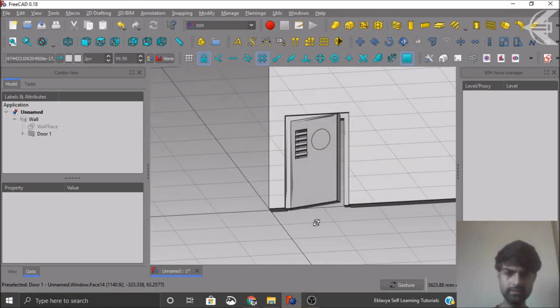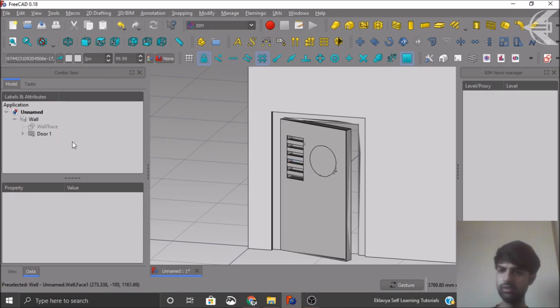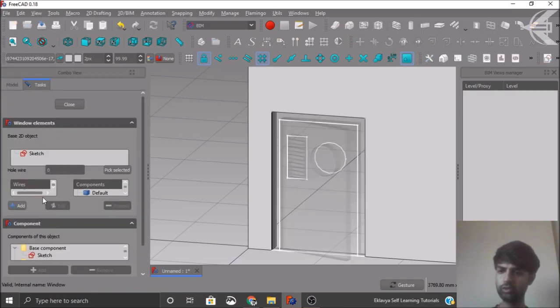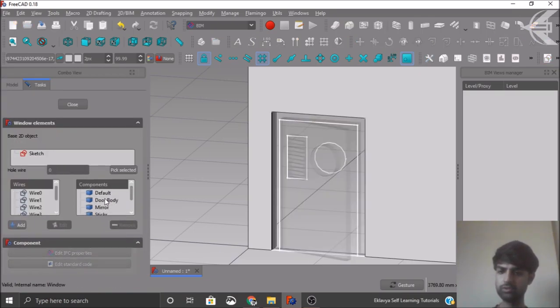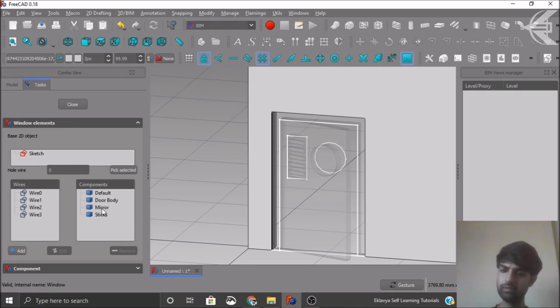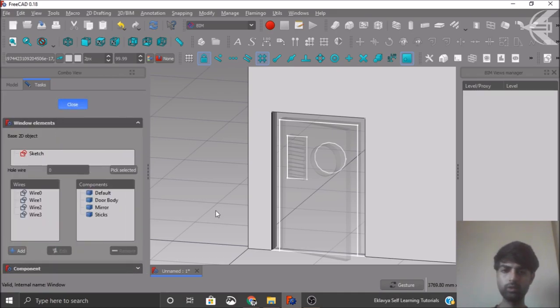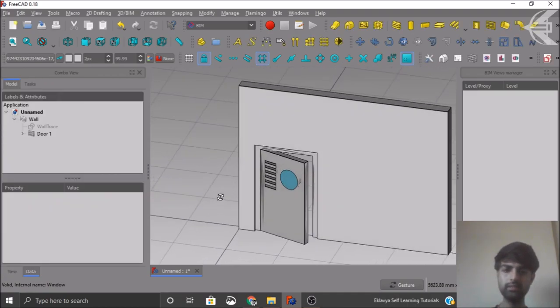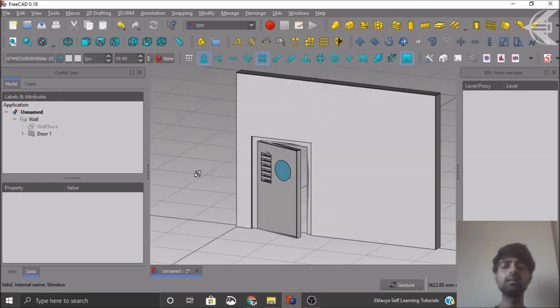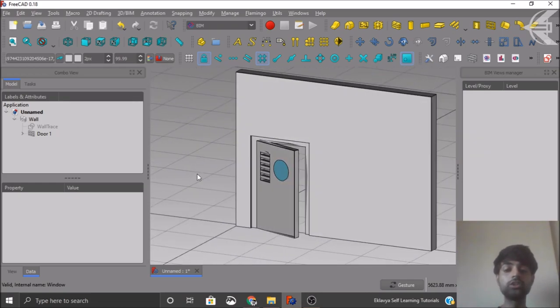So now glazing has switched off. Not a worry. Click on the door component again. It just sometimes needs to refresh it. Click on your mirror. Edit this thing. Update again. Click close. Okay, this is fine. So this was the part how you basically create your overall geometry for the door.